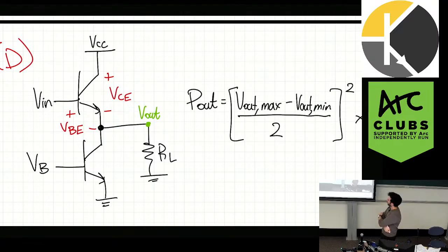You have to look at whether or not it is related to those voltages. Is it related to both of those voltages? Like, is VCE affected by V out? So VCE is the collector, which is at VCC. Where's the emitter at? V out. And same with VBE. It's dependent on the emitter.